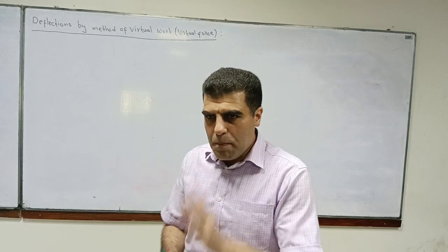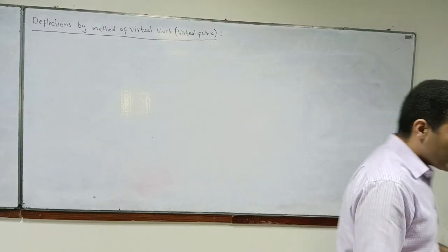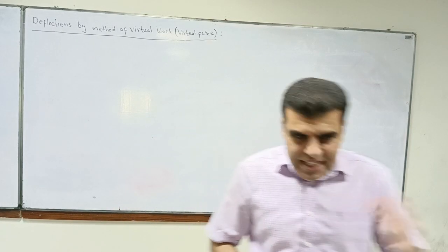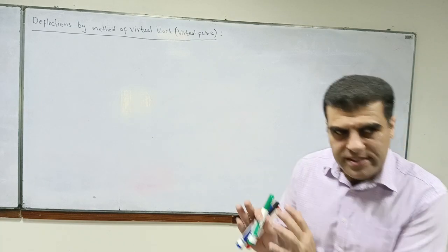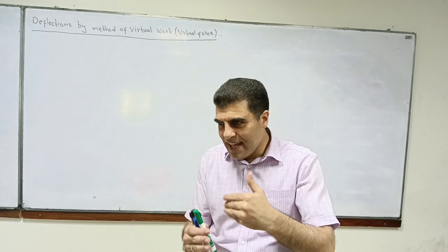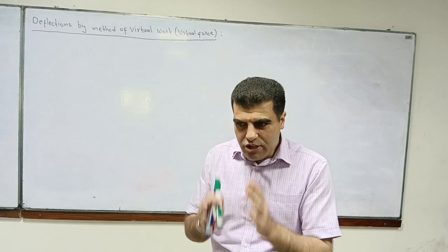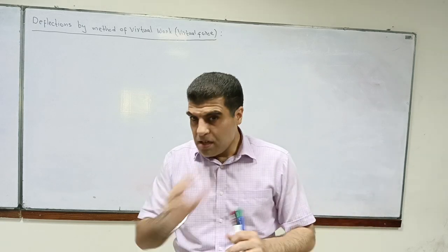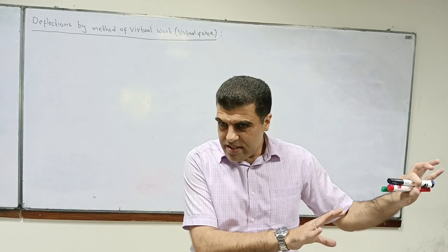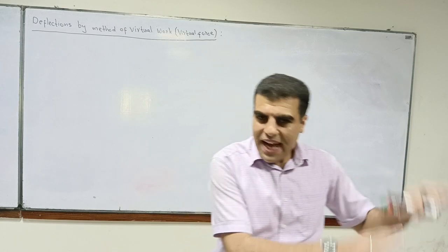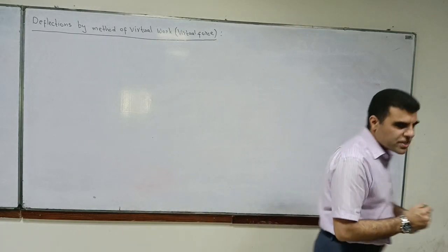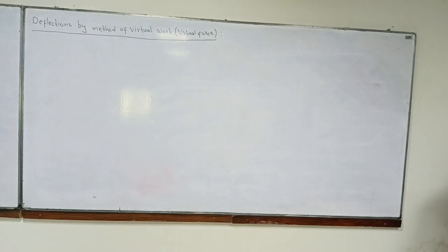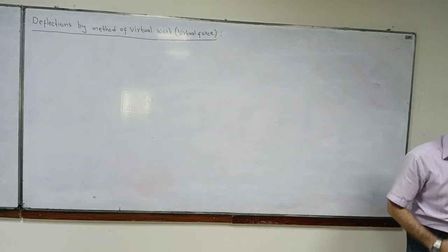So the principle of energy, or the total energy principle, is used but in a slightly different way. Why? Because we are not talking about one system where you apply the load and you get the displacements. We are taking the applied load system of one system and comparing that with another system, which is a virtual system, and finding the work done of that virtual system. So in other words, we are mixing two systems and applying internal work equals external work on it. That is the main theme of this principle, and that's why the name is virtual work method.